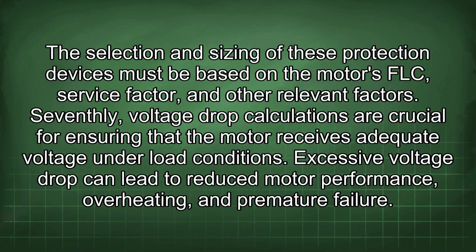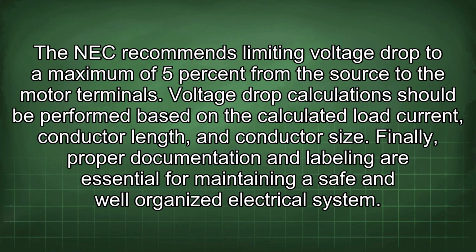Seventhly, voltage drop calculations are crucial for ensuring that the motor receives adequate voltage under load conditions. Excessive voltage drop can lead to reduced motor performance, overheating, and premature failure. The NEC recommends limiting voltage drop to a maximum of 5% from the source to the motor terminals. Voltage drop calculations should be performed based on the calculated load current, conductor length, and conductor size.